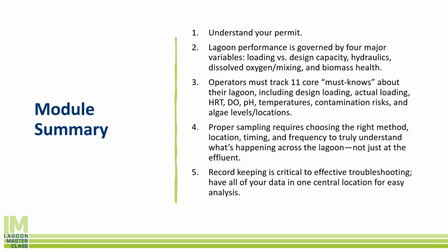You have to look at your must-knows. You have to understand your lagoon, look at the loadings, your design loadings versus your actual loadings, your HRT, your DOs, your pHs, your temperatures. Are you getting dumped on? Are you getting some kind of contaminant? What are your algae levels? How are those affecting your TSS?